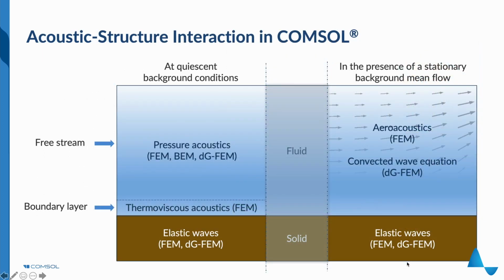Okay, so this is the product setup for the acoustics module, and what kind of physics interfaces and what kind of solver types and finite element methods are available in COMSOL Multiphysics. So we are in the free stream. The default and the widely used physics interface is the pressure acoustics physics interface. Three different methods can be used here: the finite element method, the boundary element method, the BEM, or discontinuous Galerkin